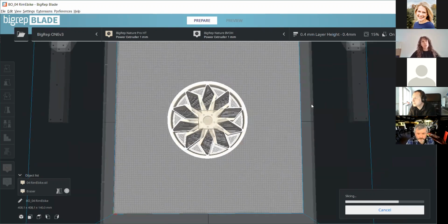So obviously you could change, for example, for this area, you could also add extra top walls, extra bottom walls. You can't change the layer height. That's one thing, obviously, that would cause an issue. You can only change the layer height if you're changing it across the board horizontally. You can't obviously change it just for the center, because if you up it or lower it, the machine doesn't know how to compensate for that, so that would cause a crash. But like I said, all the settings that are actually available will show up in that drop-down menu. So let's go to preview.